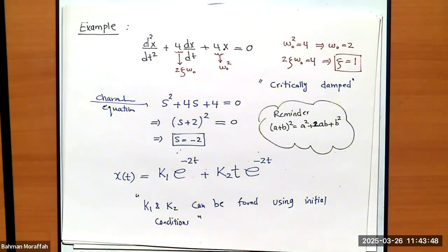What I know is if I have any RLC circuit, and if I want anything in that RLC circuit, I have to write down a differential equation, and that differential equation turns out to be a second order differential equation. And assuming the sources I have in the circuit are constant sources, I know my particular solution is some constant, which I know exactly how to compute. I just need to look at the circuit at time infinity, where I'm in a steady state condition.